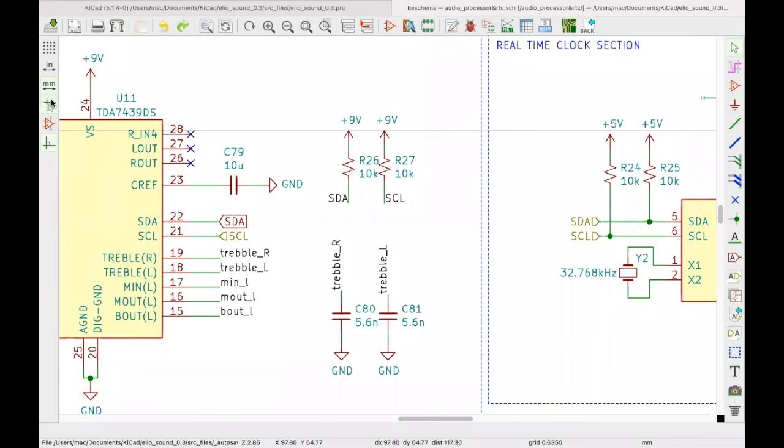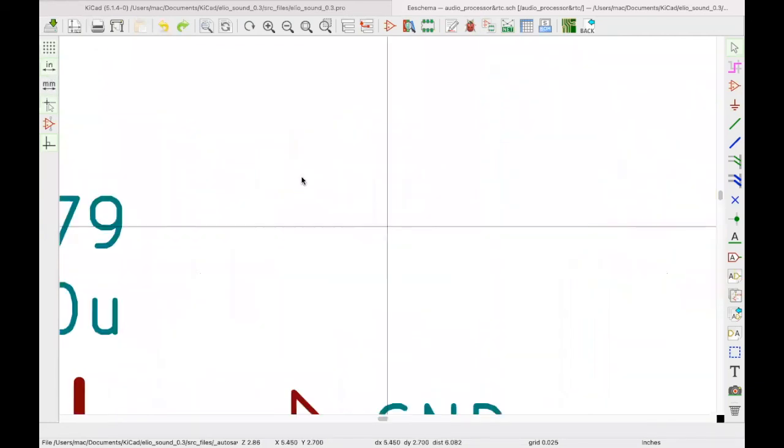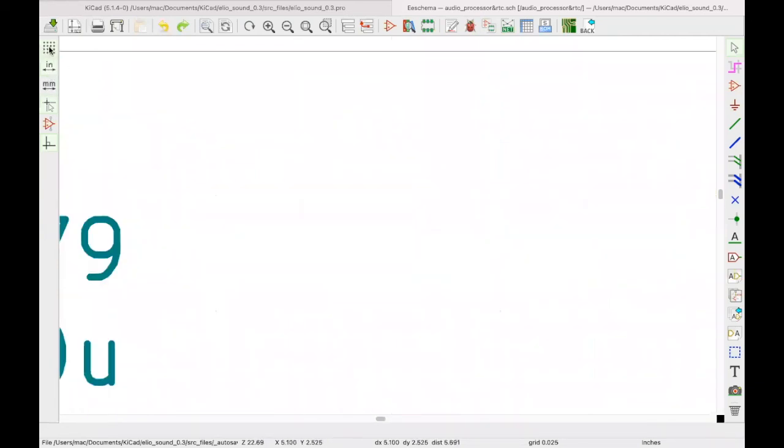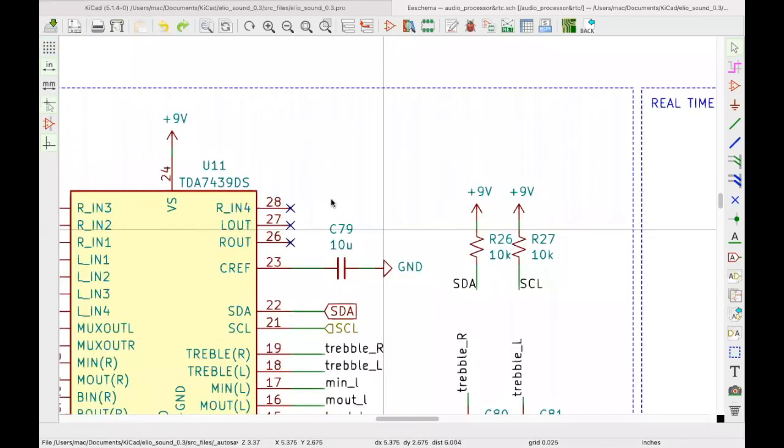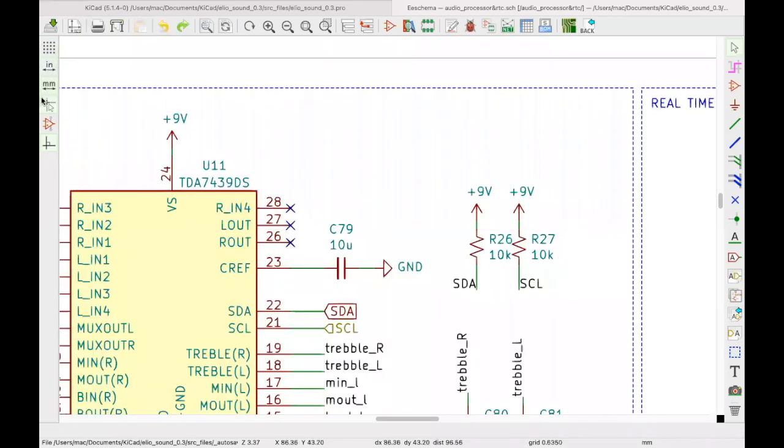Maybe one last thing to highlight in terms of commands for now for this particular design is the symbol here for units. We mostly go with the metric system. If you want to change your unit of measurement here, you can see it's highlighted in green. So here this is millimeters. If you change here, it will go to inches. And if you want to show the grid system, you can click on this. And if you want it to be a plain page, you just leave it there. I'll go with millimeters here.